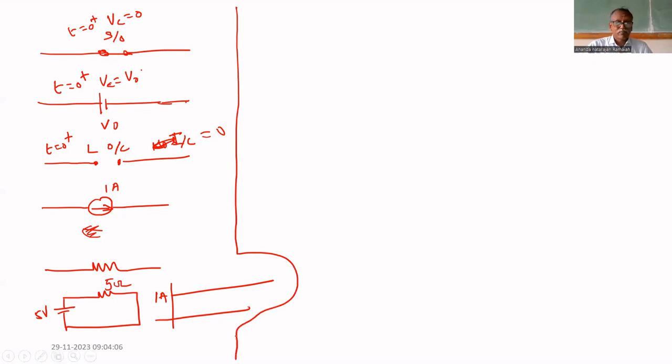That's why solving the differential equation is important, because one capacitor is there in the circuit. What is the voltage across the capacitor? VC equal to, current through this is i of t. Current through this i of t means VC equal to 1 by C integral of i of t dt, from 0 to t or minus infinity to t.